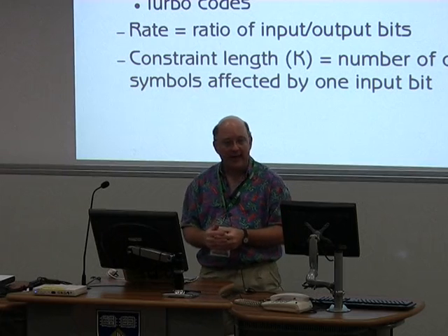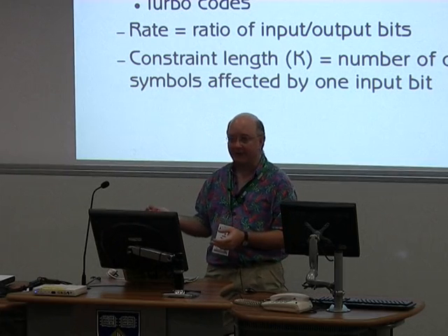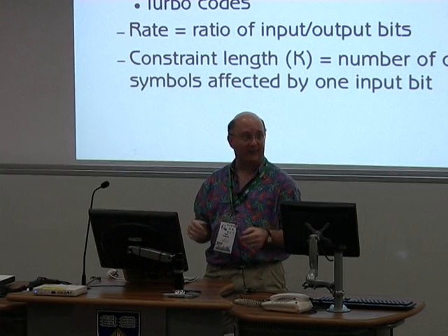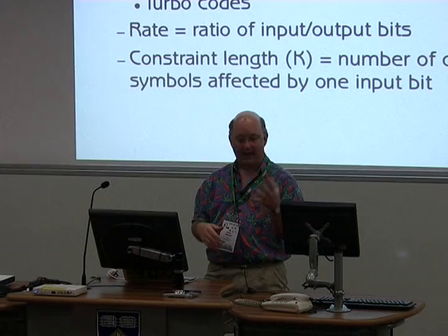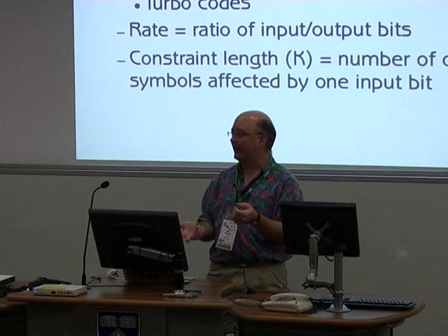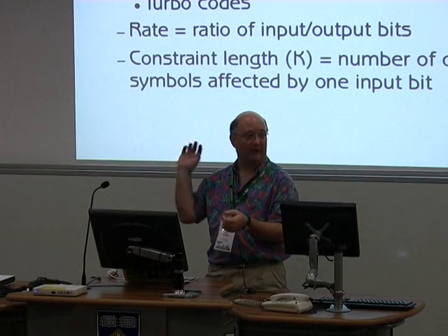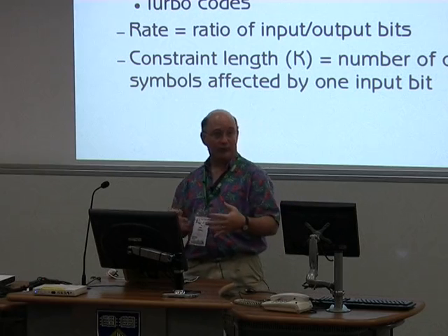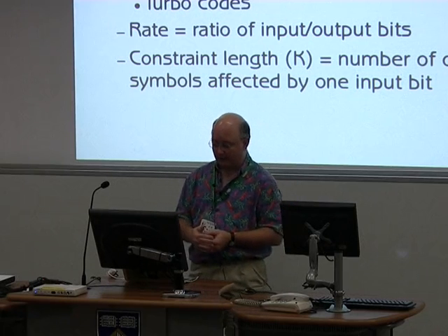If you throw away a collection of those output bits, you can generate convolution codes that have an effective bit rate of some other fraction. So if you were generating 2 output bits for every input bit, and you threw away every third output bit and used error correction to recover that data, that would be a 2/3 rate convolution code.